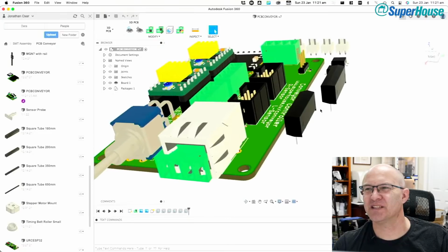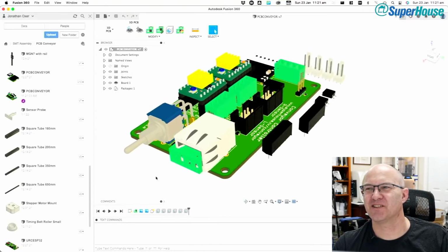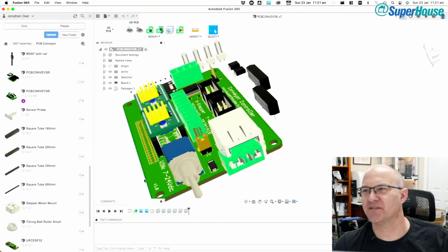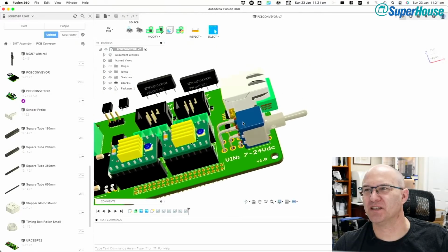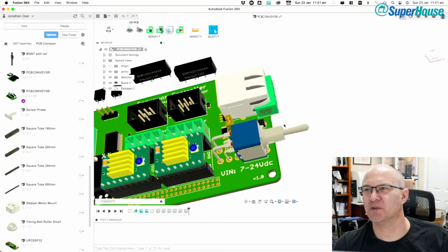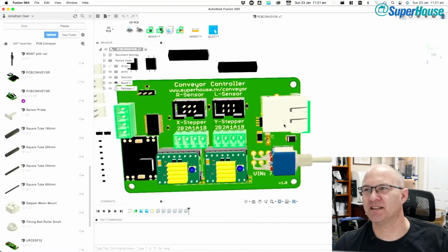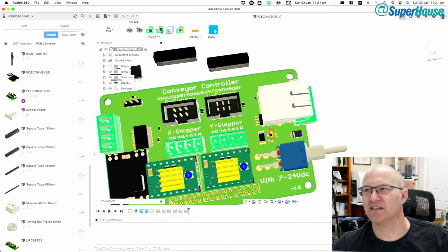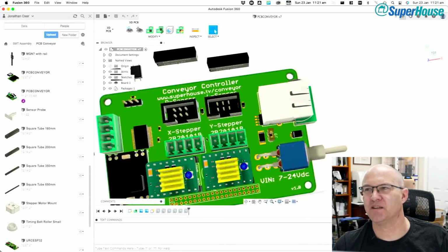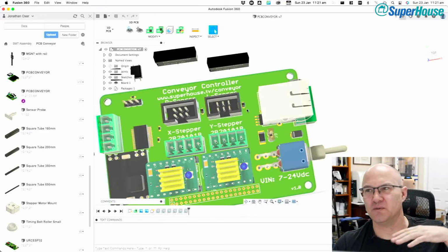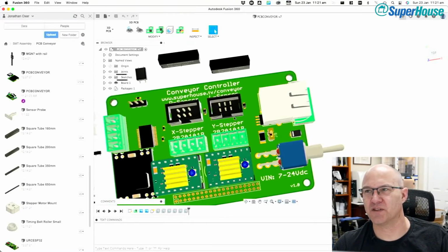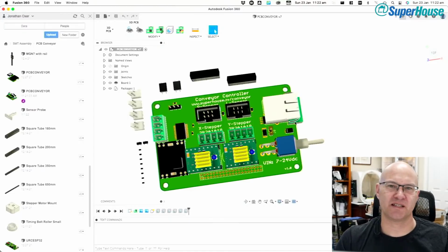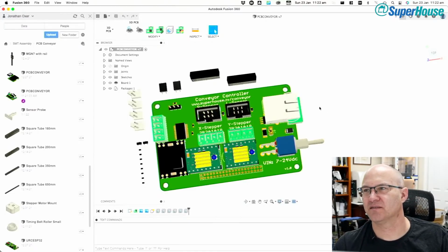All right, so it's like a teleporter accident. Two people got teleported into the same location and they're overlapping. So we've got an RJ45 or 8P8C socket there for Ethernet, and we've got the pluggable terminal blocks. You can see that the Ethernet connector is huge, and that is just the connector. Then there would be a big area on the back here taken up by the WIZnet Ethernet chip and all of the other things that have to go with it. So basically a quarter of this board gets taken up just with the Ethernet.